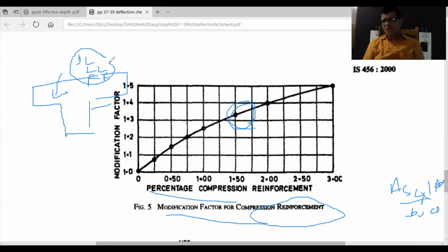Now this slab load multiplied by the area, or you can find per meter length by multiplying by 1 meter width, you will find the load per meter. So this load is to be transferred to these beams. So how will it transfer? Let us see one section. Now you have this beam here, and you have this beam here, suppose, and beams are on the 4 sides.